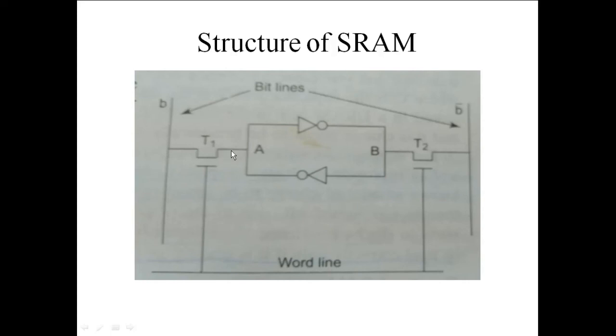When the bit information 0 or 1 is passing through the transistor T1 and reaches the point 1, this particular voltage or charge is provided to the NOT gate. So here if we have 0, this 0 is provided through this NOT gate and converted to 1, and this 1 again flows through this NOT gate, so 1 is converted to 0, and this closed loop operation continues. So once we put any charge within this loop, this charge will be rotated forever. So this is the write operation.